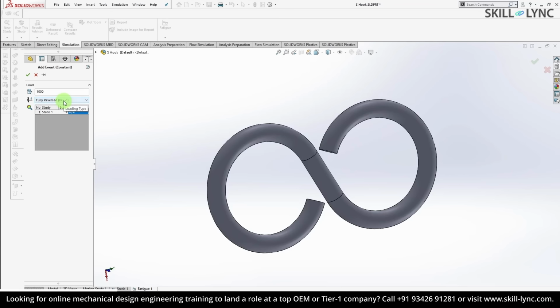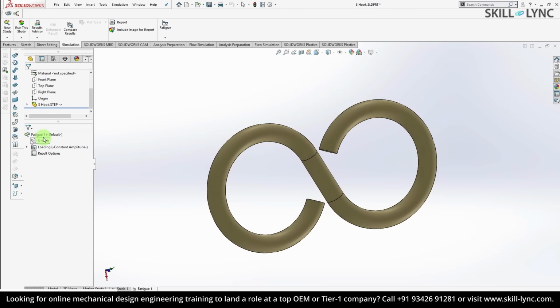Here, since we are going to apply a fully reversed kind of load, make sure you have the fully reversed option selected. I'm going to check if this part will sustain 1500 cycles for a given load and click OK.